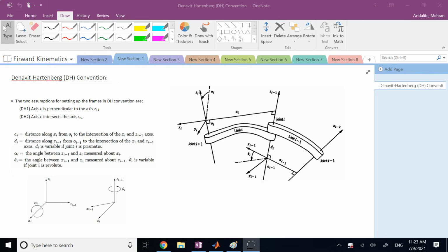Link i minus 1. Now, when we say attach it rigidly, it doesn't necessarily mean that the origin of those coordinates are on the physical object. In this convention, there are cases where the origin of the frame is going to be outside the physical object, okay? What matters is that hypothetically this frame is attached, it's like welded. For example, here you see the Oi is out of link i, but we can assume that if these axes are physical rods or whatever, this rod of axis zi is welded here, okay? So you have some welding here, and so the angle of it and the orientation of it, the position of it cannot change. So just keep that in mind. No need for the origins to be on the parts.